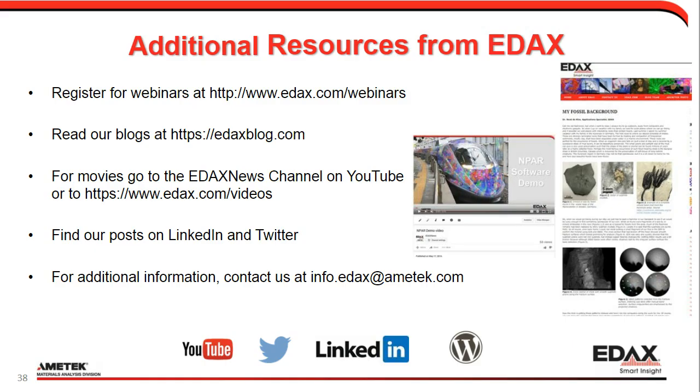Question of hardware limitations for dual detector configurations. Yes, there is. First of all, your microscope should be able to fit two detectors. Some of the smaller microscopes, you will only have space to add one EDS detector on there. Even some of the bigger ones, depending on how much other stuff you have mounted. But it's primarily which ports are available on the microscope.